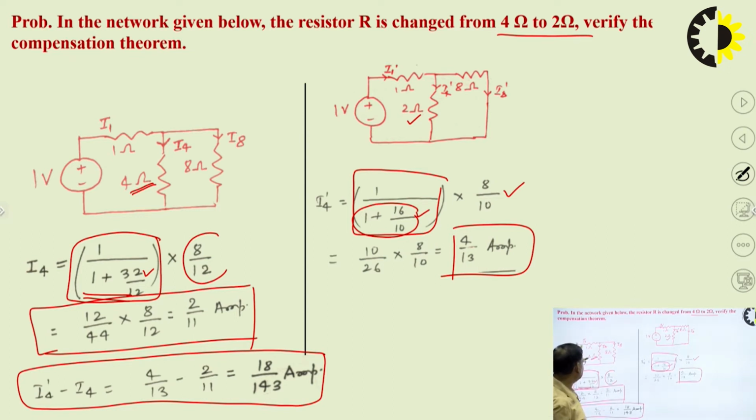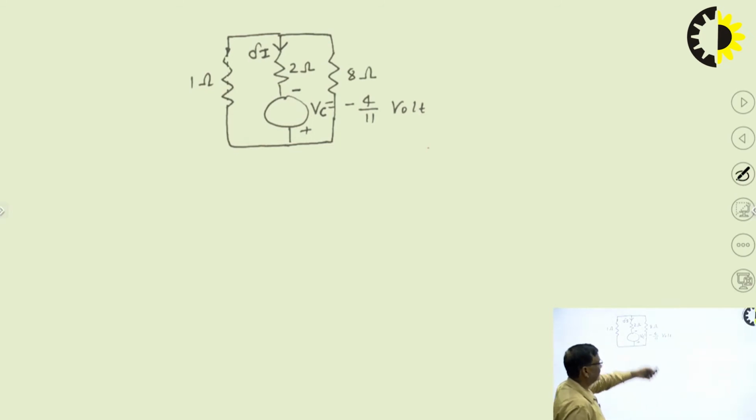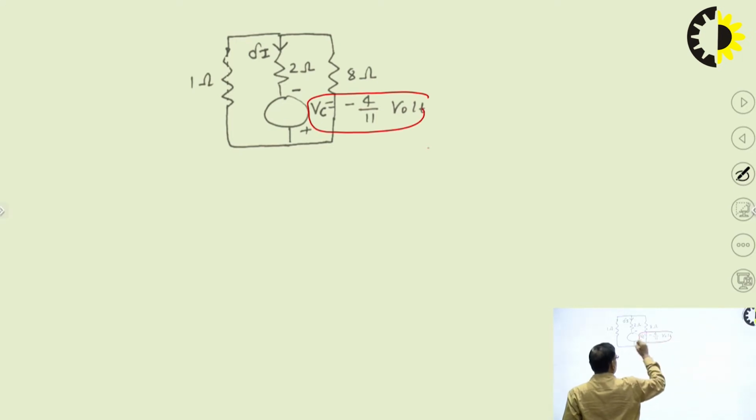So the internal impedance of this ideal source is 0, so it will be replaced by a 0 resistance wire. So look at this: this is the circuit to verify the compensation theorem. So I have injected this much voltage in the modified branch while replacing the other independent energy sources by their internal impedances.